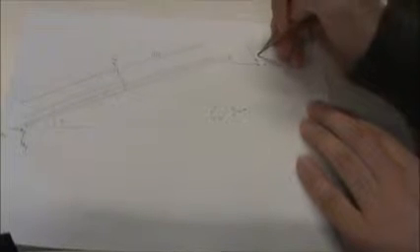So the first thing that we have to do in order to find this normal force C is to resolve all of our forces into components that are perpendicular to our moment arm axis, which is along the length of this bar. The normal force is already perpendicular, so we don't need to do anything to that. Then we have to make P, which is acting currently horizontally, into a perpendicular component to the bar. We do that by extending the axis of the bar out, and since this angle down here is theta, and this angle here is also theta, we can take P sine theta, and that will be our perpendicular component of P to our moment arm.